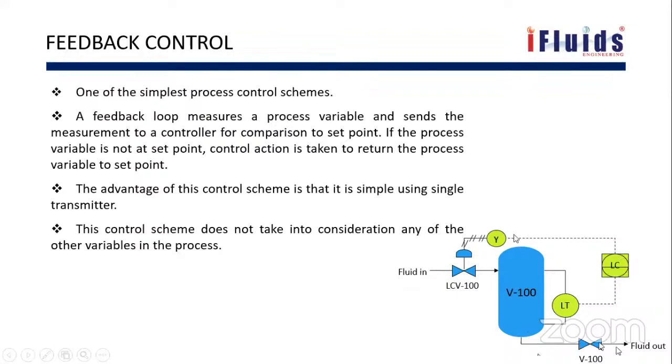So this is a simple control which only maintains the level with the help of inlet fluid flow. Okay. So the same can be replicated for the outlet also. In a few processes, we'll have this control valve in the outlet, so level will be controlled with the outlet flow. So that can also be there. The valve can be provided in the upstream or in the downstream.